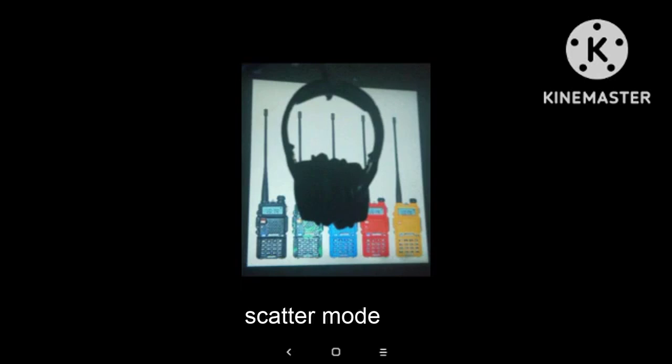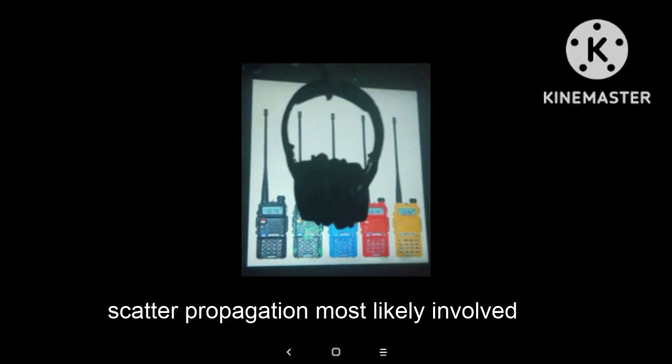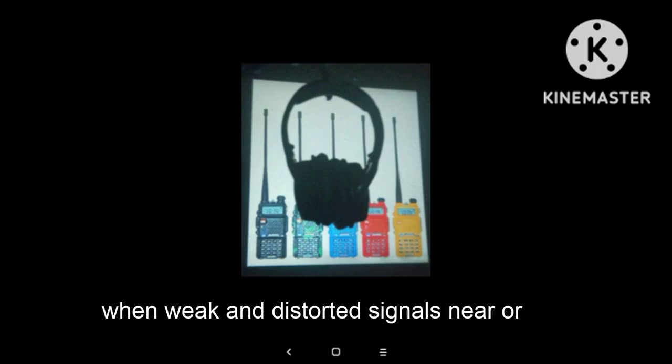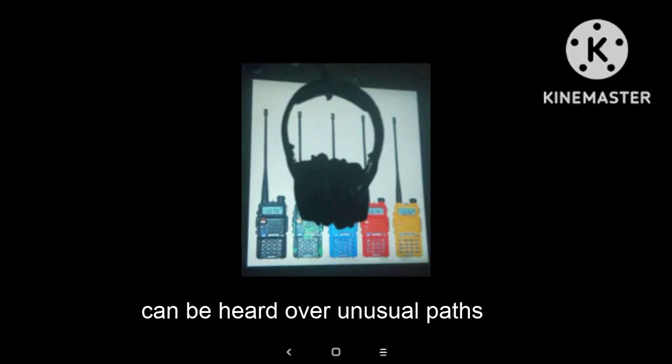Scatter mode. Number 8. On the HF bands, when is scatter propagation most likely involved? When weak and distorted signals near or above the maximum usable frequency, MUF, can be heard over unusual paths.